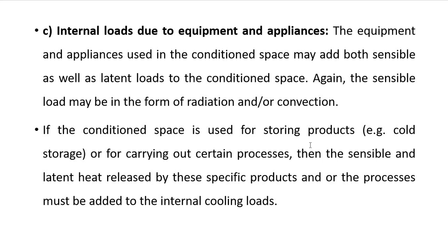Now, if suddenly a new bulk of milk packets at 25 degrees Celsius is brought into this cold storage, the temperature of the milk has to be reduced to 10 degrees Celsius. That is the cooling load.